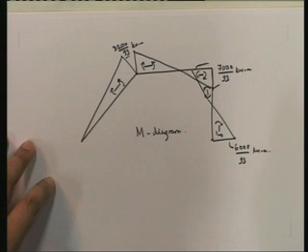Because as I said, normally all members where the two joints at the two ends are continuous joints, you will always have a fixed member. So the member force relationship is very simple. If you have a member load, then you have to compute the fixed end moments. If you don't have a member load, then you don't need to compute the fixed end moments. Next is, if you have one end of a member which is a support, and that support is a hinge support, we can eliminate that degree of freedom and use the modified member force deformation relationships.